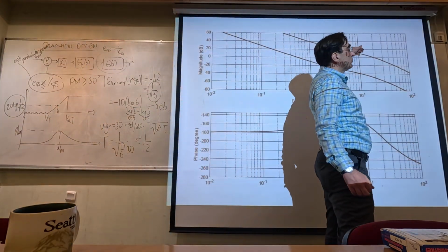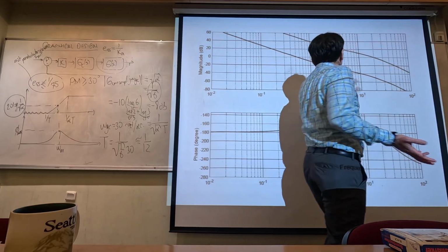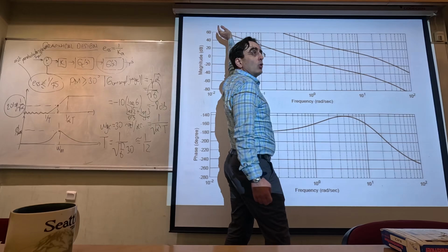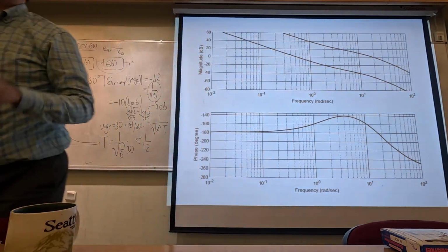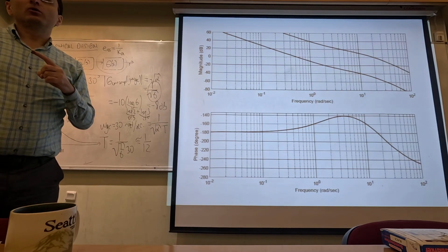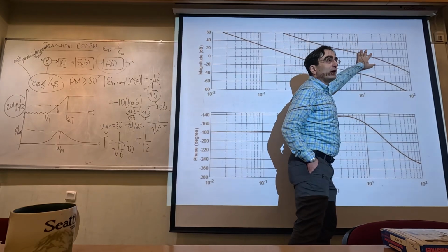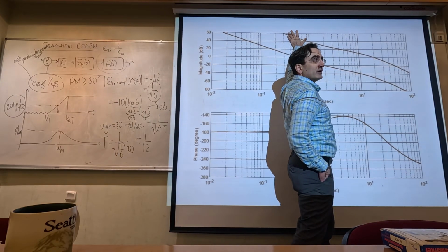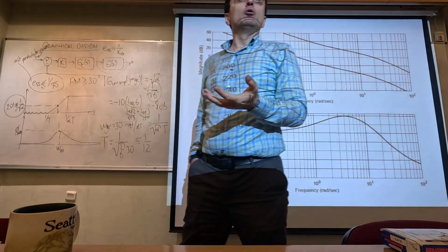If you choose your gain smaller, the phase of the system is going to increase, but for steady state error performance, you will decrease this waveform at low frequencies as well with a single gain. But we can do the same thing with something called a phase lag compensator. If I can decrease the gain only somewhere around here, and keep the gain the same at low frequencies, then I can always achieve this. That is called a phase lag compensator.